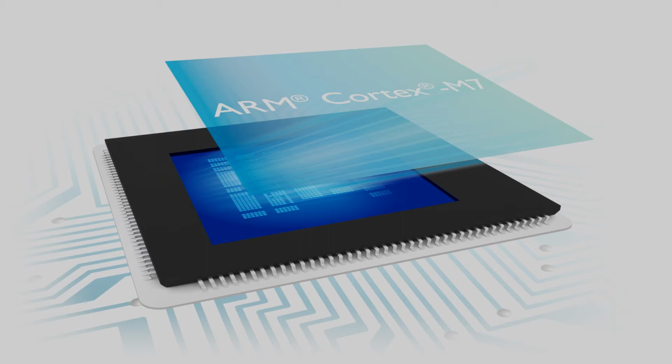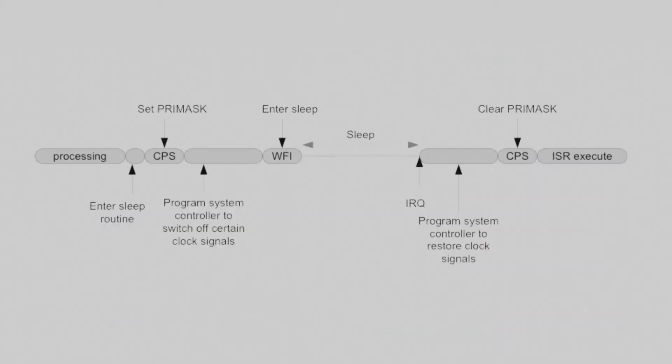Today I wanted to show you how the sleep mode of any Cortex-M processor core is entered. Every manufacturer has his own exact implementations for how sleep and standby modes are entered, but there is only one useful call to stop the core of any Cortex-M processor, and that's the same for any manufacturer. The WFI instruction. WFI stands for wait for interrupt.